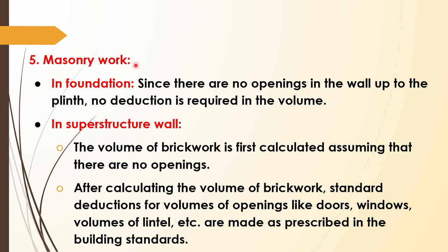In foundation, since there are no openings in the walls up to the plinth level, we will not give any deductions. For example, if you're seeing a foundation, there are no holes in the foundation. We will not provide any holes, right? So there is no deduction. For example, if we need 100 bricks, how much is the volume of bricks needed for making the foundation, we will take. No need of deducting anything from that.